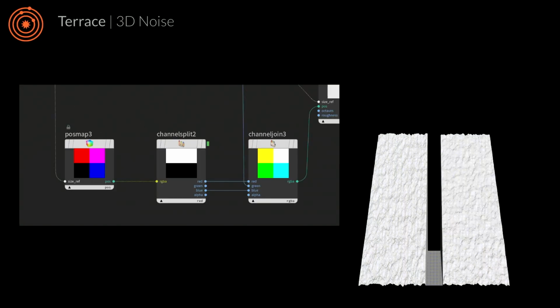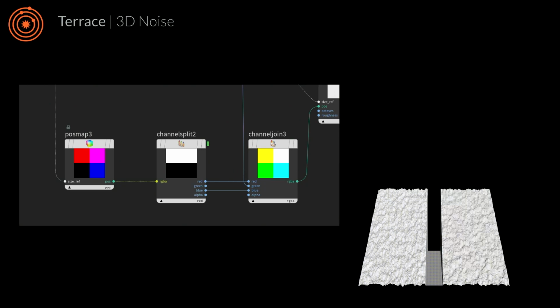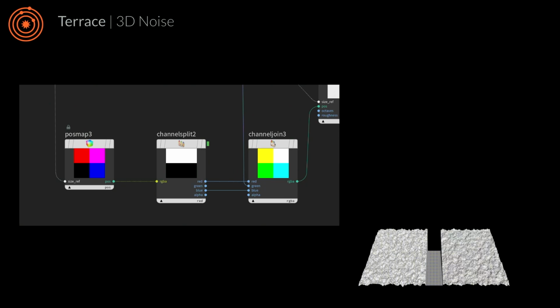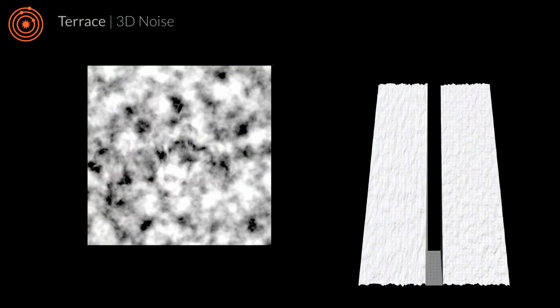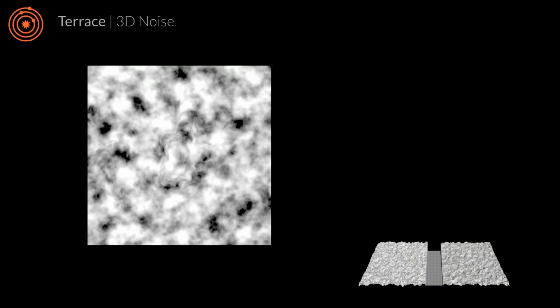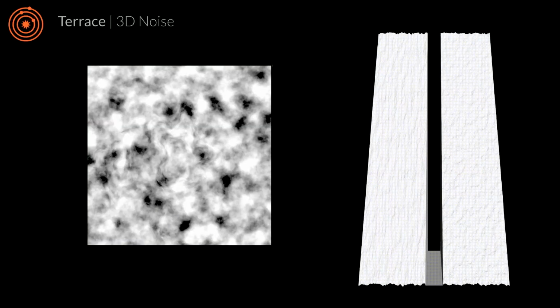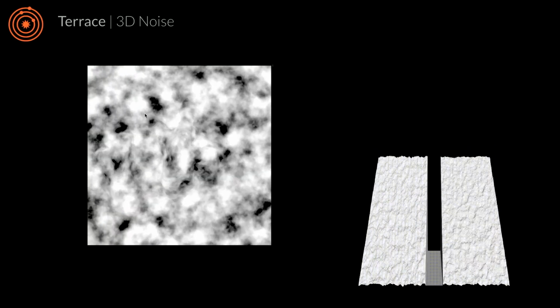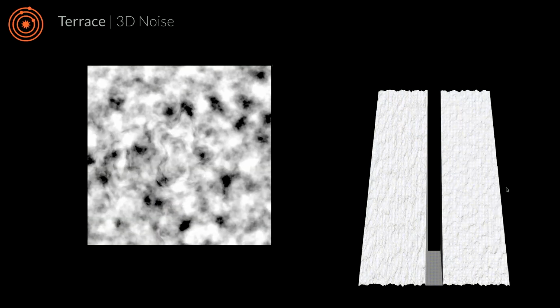And specifically, you create a position map, you channel split it, and then you replace your green channel, which is your height, right, with your height map. And now if you preview your 3D noise, this is just the 3D noise layer, but it's already adjusted. You can see some of the height field kind of outline happening in the middle. It's already adjusted to my input height, and therefore we can achieve this result here.